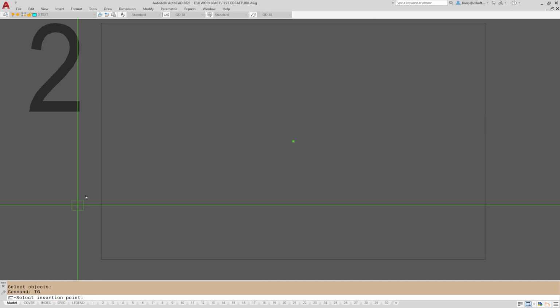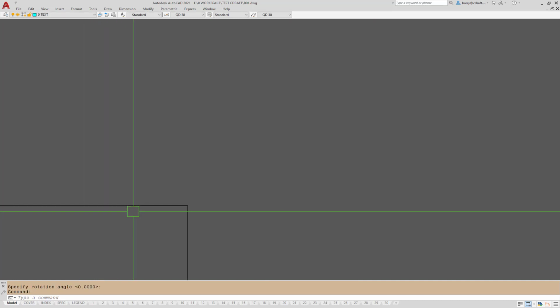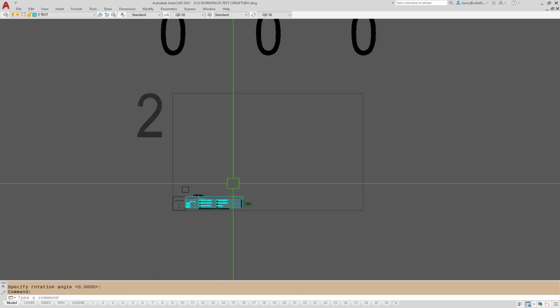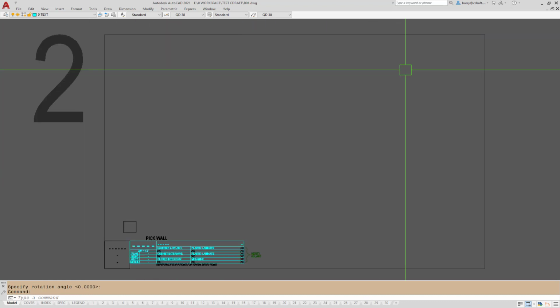So I'm going to start back on 0, so to speak, and we're going to enter a tag, and that just simply reset my base point, my insertion point, to right here. Let's move out to the right hand side, get out of the way, so we'll do an F1 again. Filler, let's do 3 inches is fine. We're not going to do countertops or base cabinets, so spacebar.